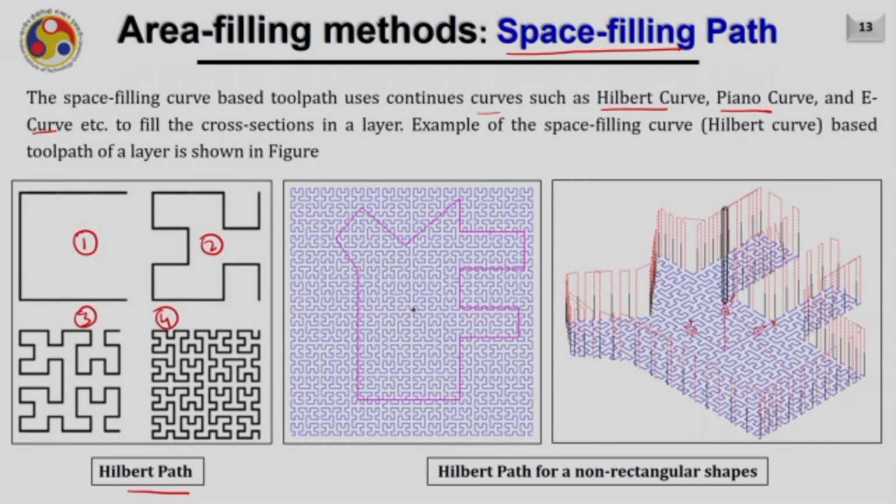This type of tool path very nicely follows the four requirements we discussed. Let us see here, the number of switch offs and ons is very low. Also you can see the step over is maintained everywhere. Everywhere if you measure the distance between two consecutive passes, anywhere it will remain the same. But the issue with these tool paths is that they are not capable of obtaining any random geometry.